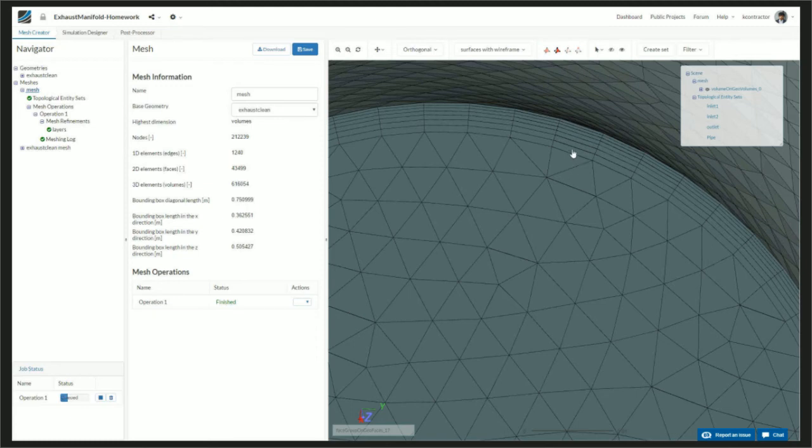And this ratio between the last layer and the first layer of the mesh outside the layer should also be not too big. Otherwise, this would also cause problems in the solver. This would basically cause very high gradients in the solver, which is a really deep topic to discuss right now. But let's just say that the volume ratio between this cell and this cell should not be too high.